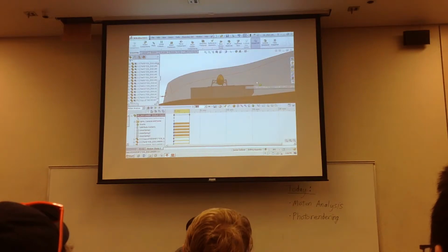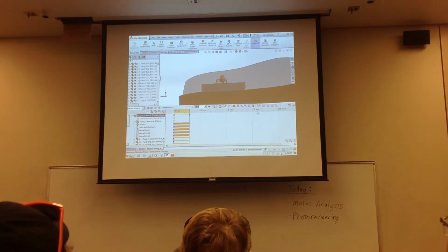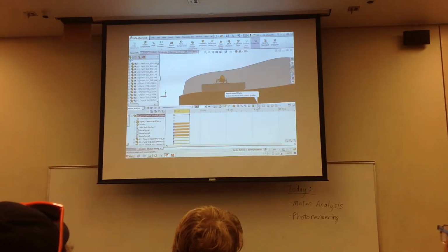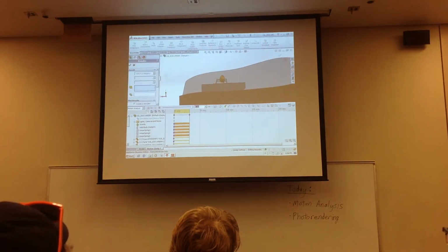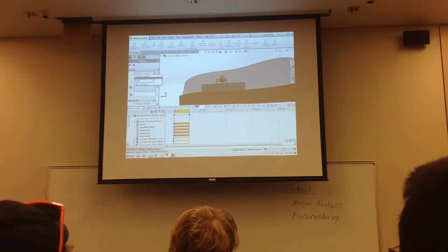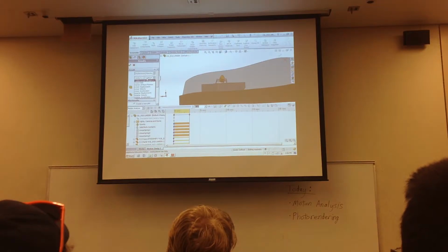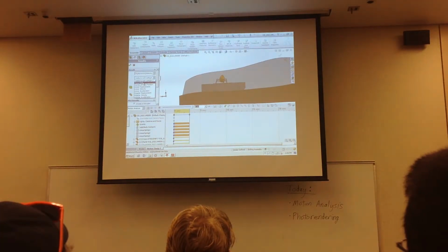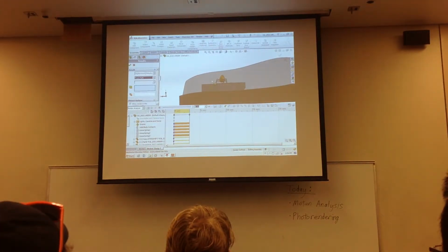Okay. So to produce results, we use this button right here that looks like an XY graph. Click that and we can first choose a category. You can do forces, momentum, other quantities. For right now, we're going to do displacement, velocity, and acceleration. And then we choose a subcategory. The first thing I want to show you is the trace path. So I'll click on that.